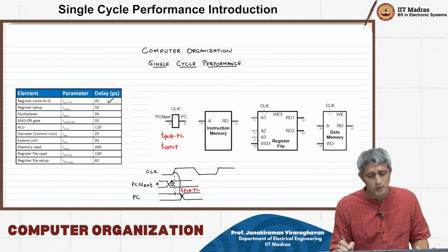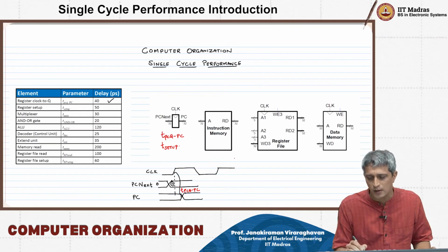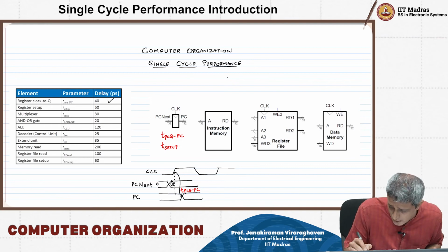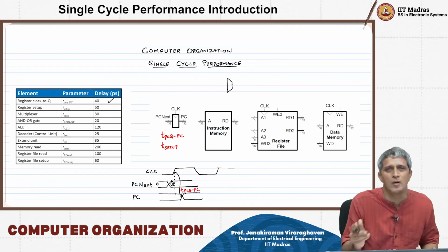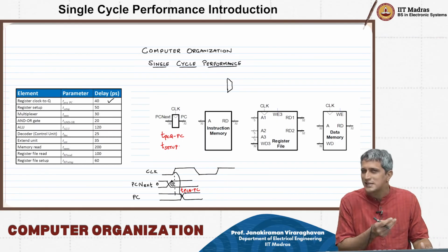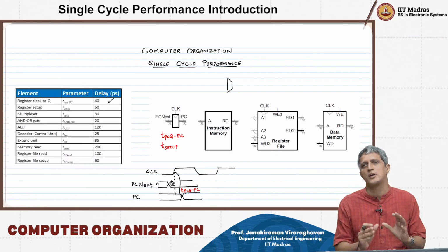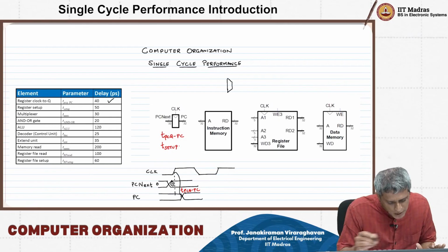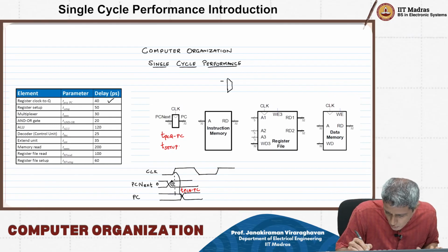After that, what is not shown here is also we did have a couple of multiplexers, right, simple 2:1 multiplexers like this, right, or maybe 3:1, 4:1, right. So what is a multiplexer? Basically a multiplexer is nothing but a decoder followed by a tri-state inverter, right. So there is a mux delay that we are going to talk about, right.